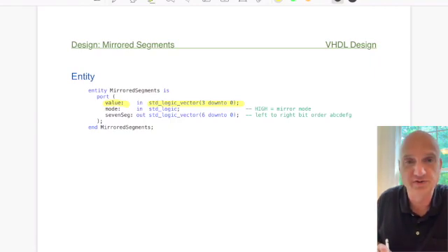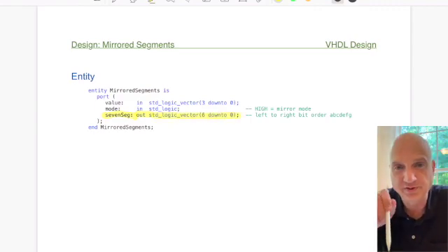And we're going to assume that this is basically a standard numeric value with the most significant bit being bit 3 and the least significant bit 0. That's pretty much standard across the industry if it's not specified. The next thing is the mode, and the mode is just a standard logic input. And then the next one would be our 7seg, which is an output, and it is a 7-bit output. Each bit represents one of those segments.